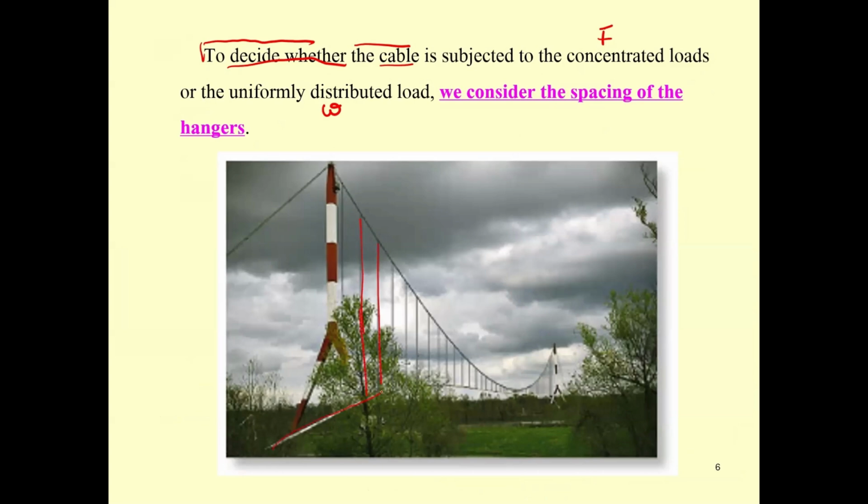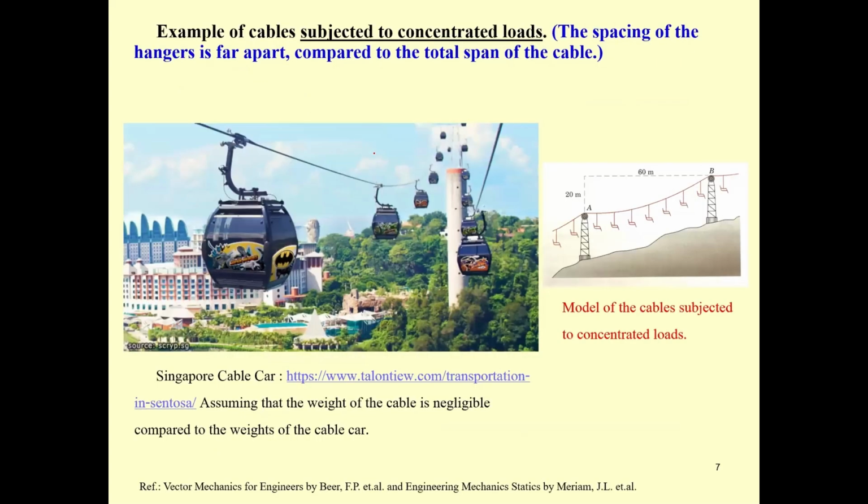We have the pipeline to transfer the crude oil from one side to the other. If the distance between the hangers is small, we may assume this to be distributed force. But if the distance is large, we will assume it to be concentrated load.